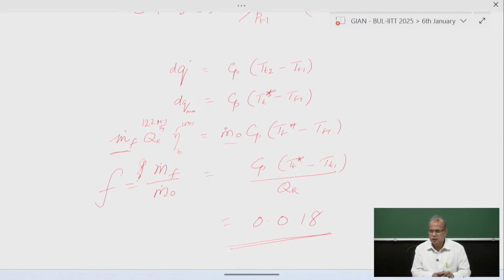All of you have finished this one? So you got the grasp about what we did today. This morning we went through the overview of the gas turbine powered engines. We looked at the turbojet engine, and the turbojet with an afterburner, and their corresponding cycle diagrams. Afterburner is used for thrust augmentation. You use it only when it is required because it also carries the penalty of fuel consumption.